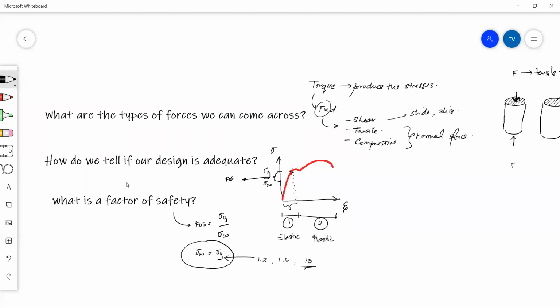Now, these different factors of safety are industry standards. So for different applications, different parts have different factors of safety. If you know the material very well and you know relatively accurately the kinds of forces that will be exerted, then we have a lower factor of safety. But if there are a lot of unknowns, a lot of unpredictable things that can happen, we have a higher factor of safety. So these kinds of things you have to keep in mind when you approach this assignment. Okay. Are there any questions just on this? This is just all background theory and background knowledge.